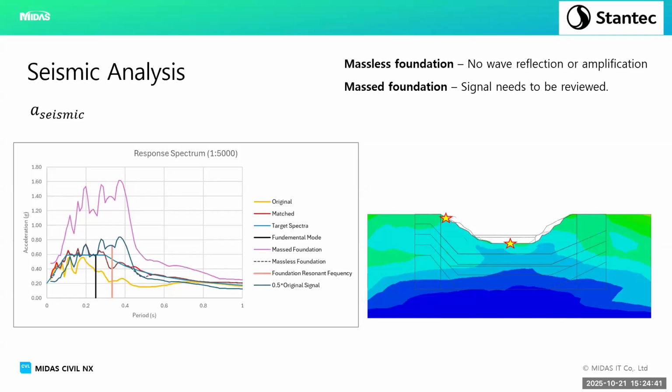is run a 2D analysis. Because if you put, say, a 1 g signal or 0.7 PGA seismic event in there, that 0.7 might not even reach the top, because your shear strains might be so great, your soil damping is large and it doesn't carry the signal up. But what it does do is go through period lengthening, or change the frequency content of the signal. That's critical to know, and you can't capture that in a response spectrum from the code.